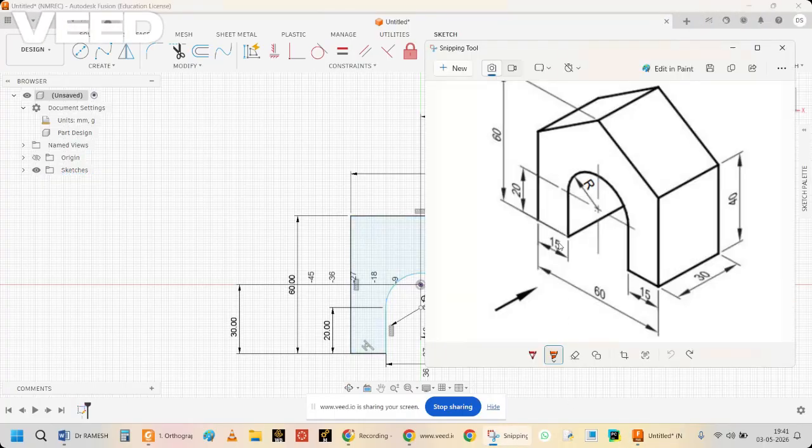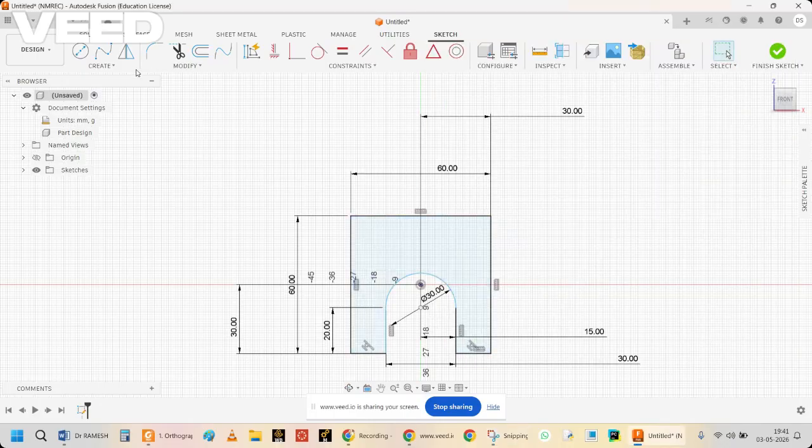Now the next step is, at the top it has a triangular shape. Can you see that, a heart-like shape? So the top surface edge, the top point is 60 mm, whereas on the other side it has 40 mm. So from 60 to 40 mm I have to draw these two inclined lines. So how do we create it? For that I have to draw one more line.